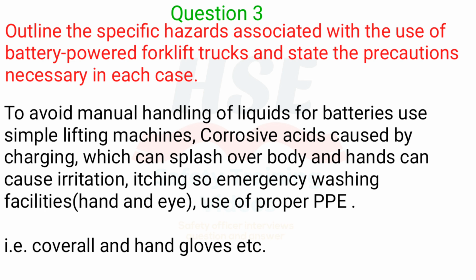Corrosive acids caused by charging, which can splash over body and hands, can cause irritation, itching, so provide emergency washing facilities for hands and eyes, and use proper PPE, that is coverall and hand gloves etc.